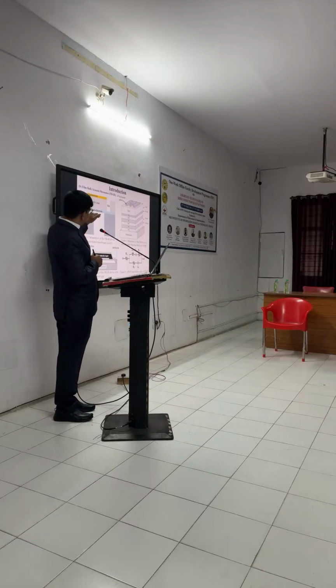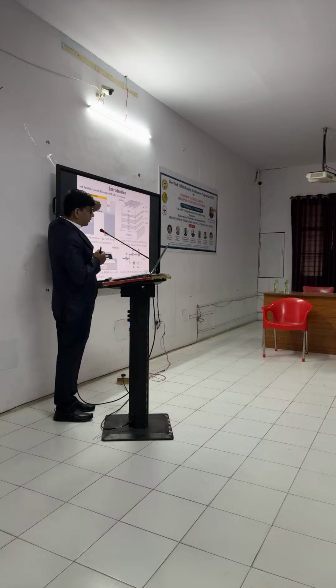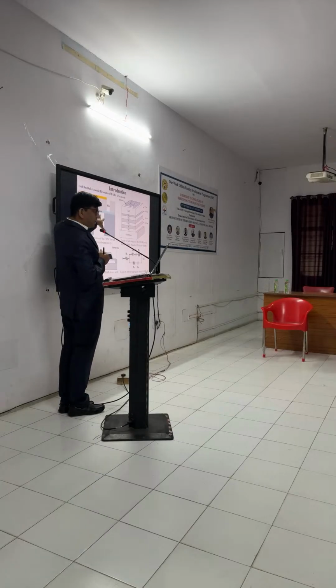But again, for this FBAR also we require a confinement of the acoustic signal within the piezoelectric layer. So how can we confine our acoustic signal into this piezoelectric layer? We have different kinds of structures for this acoustic device. First, we have an air cavity type structure. Here we have a silicon substrate.